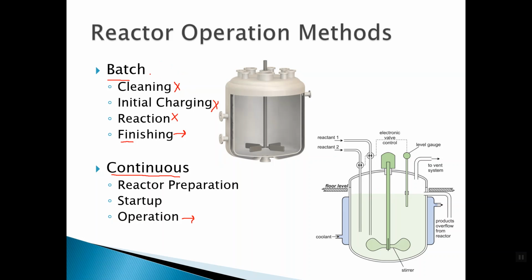Okay, the reason we use batch in the lab and in the ethanol industry is this component right here, this cleaning. Since ethanol fermentation is a bioreaction, that means it's a living reaction. It is subject to contaminants. And so if we get any type of harmful bacteria in there, that's going to kill off our yeast, which is our catalyst, and the reaction won't work properly. And so we have to dump the material out, use it up, and then clean the vessel out.